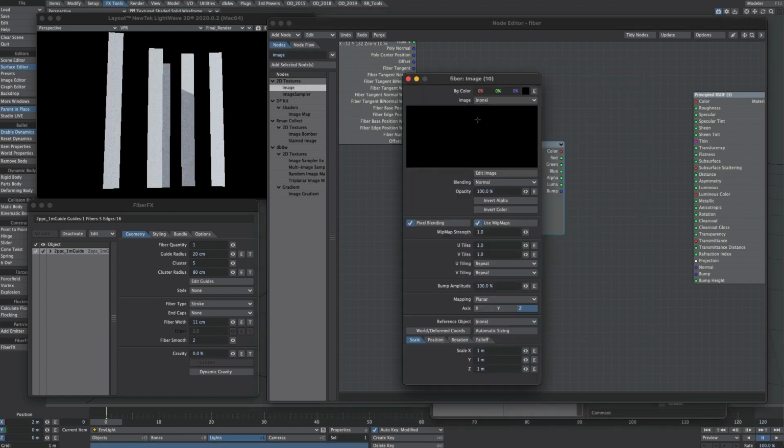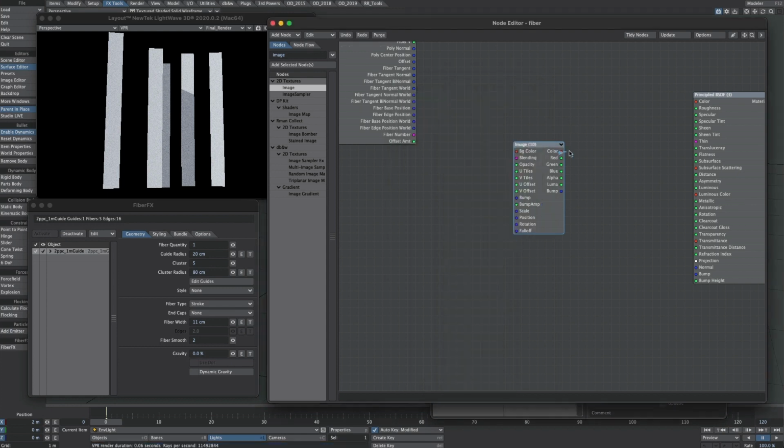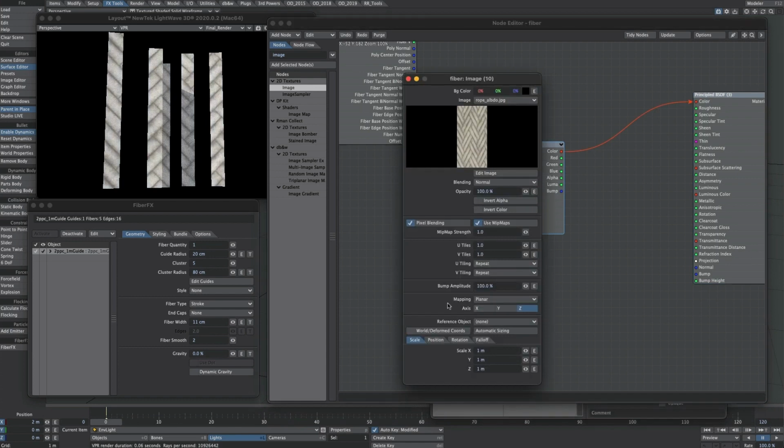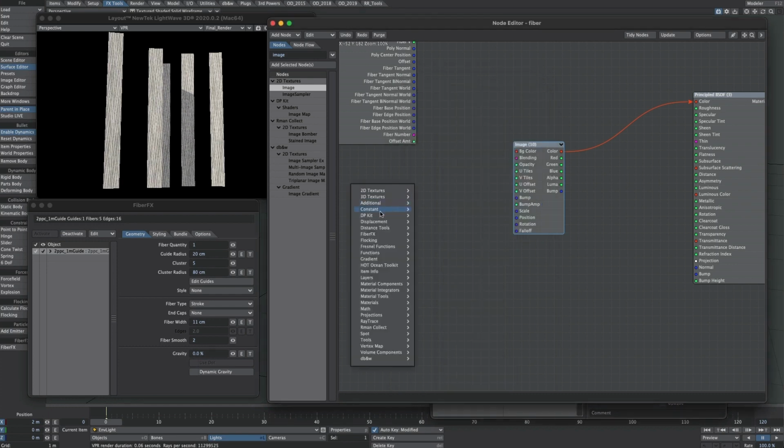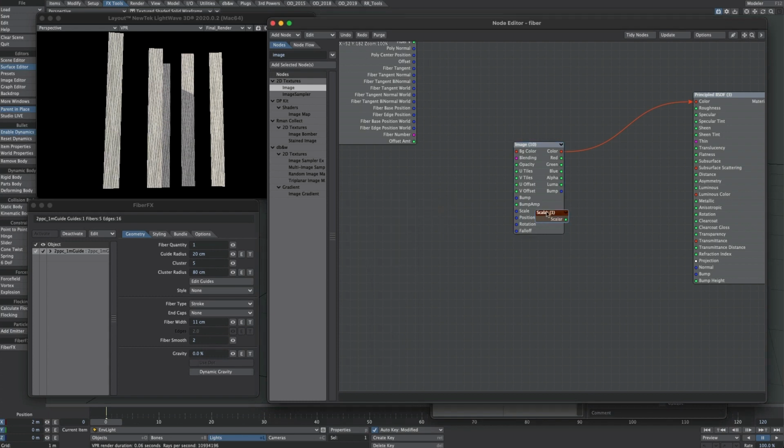I've already loaded a couple of PBR image sets to demo. So for the image type, I've got a rope, and I think it's the albedo here. Let's plug that in. Now, as we used in the 2D texture, let's open this up. And for my mapping, I'm going to change that to Object UV. So we immediately get results here, but let's go for a constant scalar. And we'll plug this into the tile of the V, and we'll perhaps increase that just so they're not so stretched.